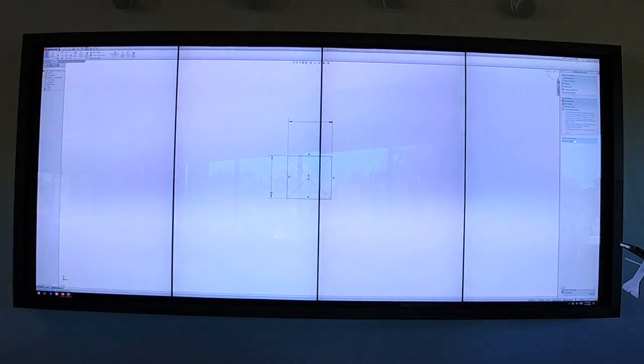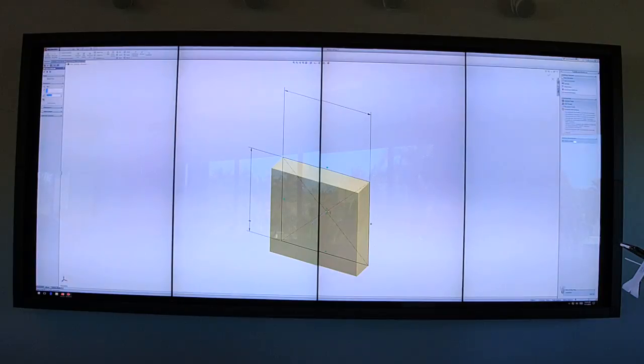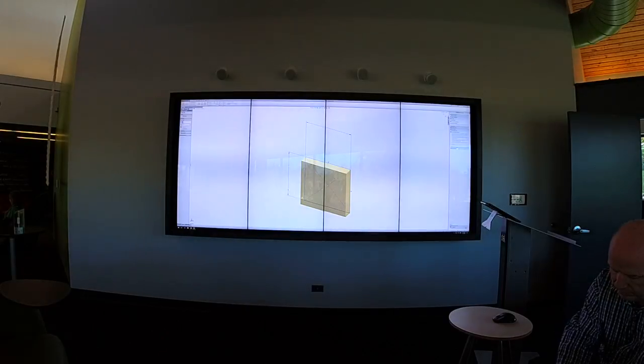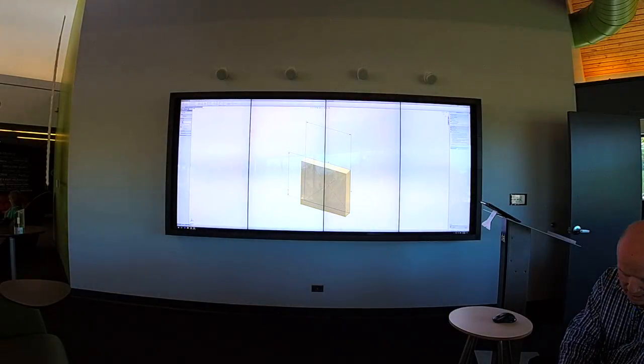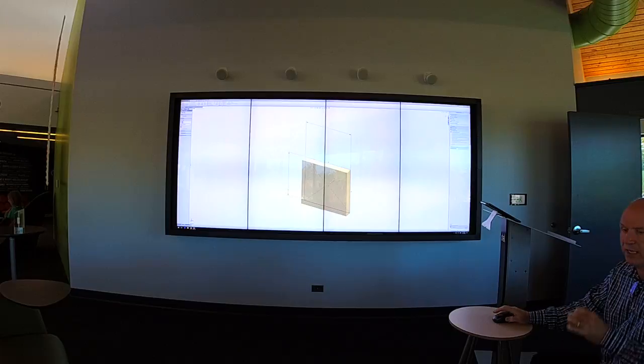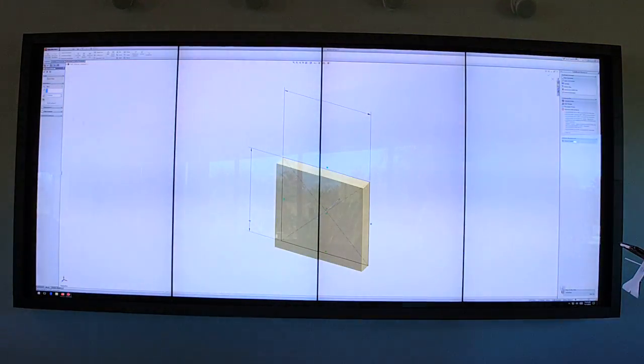One of the ways you can do that, at the top you've got an extrude boss. Two options here: you've got extrude or cut. But right now we're going to extrude. And with our extrude, we've got a couple of options. Number one is that we can actually drag it and kind of pull it out. Or we can set a specific size right here. Now, I know, for instance, my printer uses 0.223 inches as a thickness. So if I do that, 0.223, and then just say inch, it will make that the specific thickness, which is approximately 5 millimeters. Once I'm happy with that, I click OK.